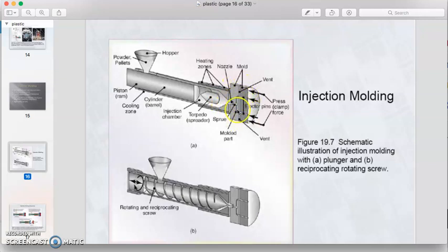So at the right end of the injection molding machine is where the mold of the injection part is located. This is also the mold. So the difference is only how we transfer the raw material to the mold. Here in the above figure, the piston or ram will move to the right to force the raw material to pass through the nozzle and the runner and fill the cavity inside the mold.